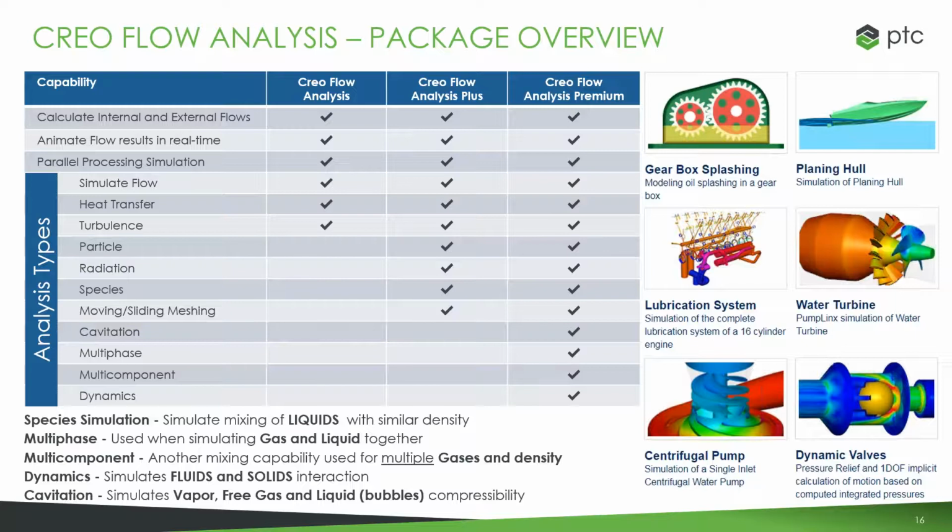Another thing I would mention is that the example we saw was an internal flow example, but this tool is also quite capable of doing external flow, which would include natural convection. So if you're designing something, maybe automotive or something like an LED light, which does not have a cooling fan, it's quite capable of giving you good information on that. You have to go in and define gravity, and it's not too much more complicated. You do have to define a computational domain, but there are nice tools in there to do it. It'll take you about 5 minutes and you're good to go.